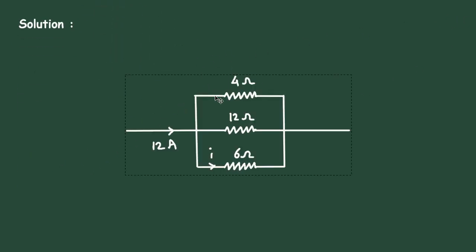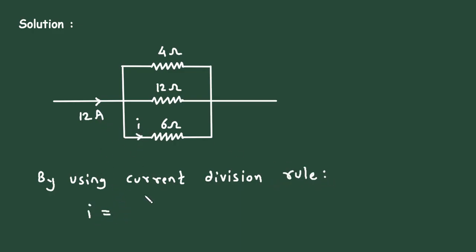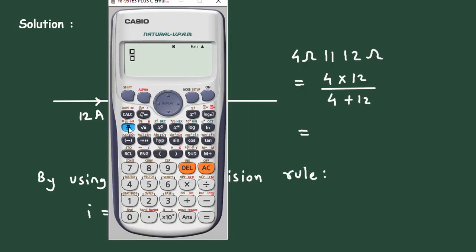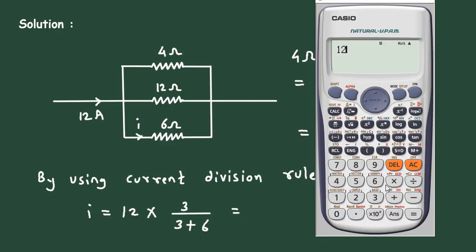So therefore the value of current I1 is 3 multiplied by 8 divided by 8 plus 3 plus 1. So it is 2 ampere. So the current through this ammeter will be 2 ampere. So here we can write ammeter current is equal to 2 ampere. So this is what we have to find in this question.